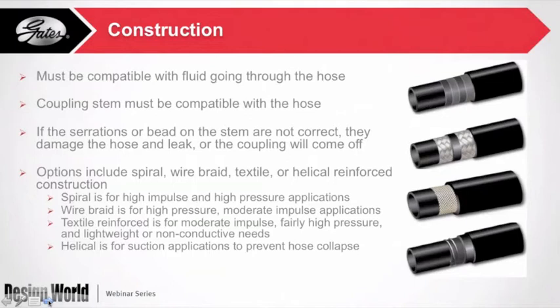Some of the hose constructions that these couplings are going to have to work with, and there's a lot of these hose constructions out there, range from everything from a 6-spiral hydraulic hose that can handle up to 8,000 psi of pressure to a mud transfer hose, for instance, on a drill rig top drive system that could see up to 7,500 or even 15,000 psi demands if you get any kind of shock load on these systems.